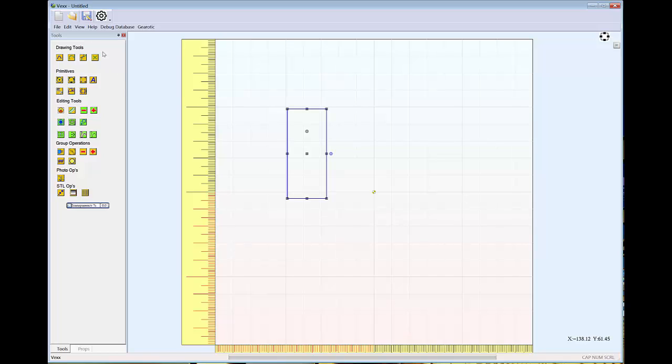If you group something, however, it has memory. If we go to Edit, Group, you can group any group of lines, contours, together into a single group. This group now will remember where I put its rotational center, even if I'm selected away and doing something else. This rotational center will also be copied or array copied to other groups when you deal with adding groups together.